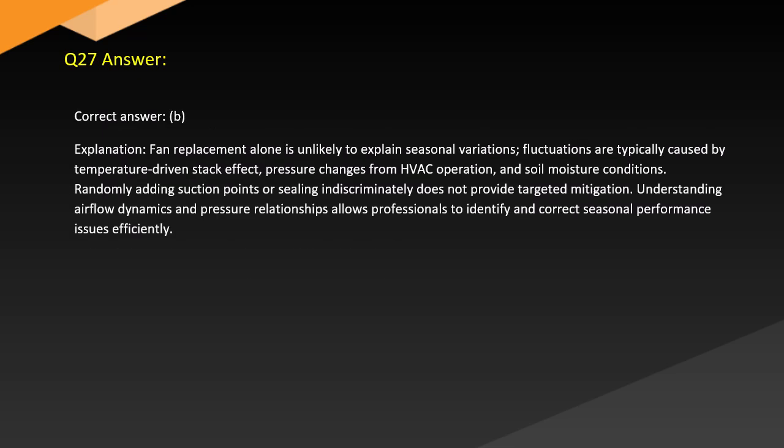Answer. Correct answer: B. Explanation. Fan replacement alone is unlikely to explain seasonal variations. Fluctuations are typically caused by temperature-driven stack effect, pressure changes from HVAC operation, and soil moisture conditions. Randomly adding suction points or sealing indiscriminately does not provide targeted mitigation. Understanding airflow dynamics and pressure relationships allows professionals to identify and correct seasonal performance issues efficiently.